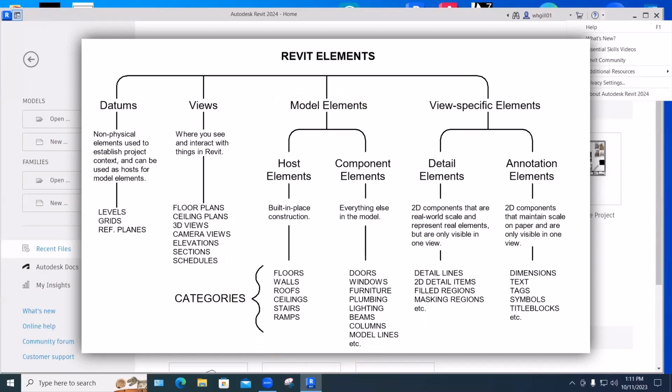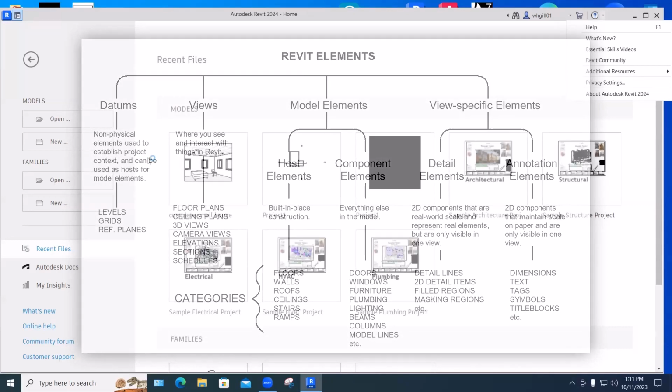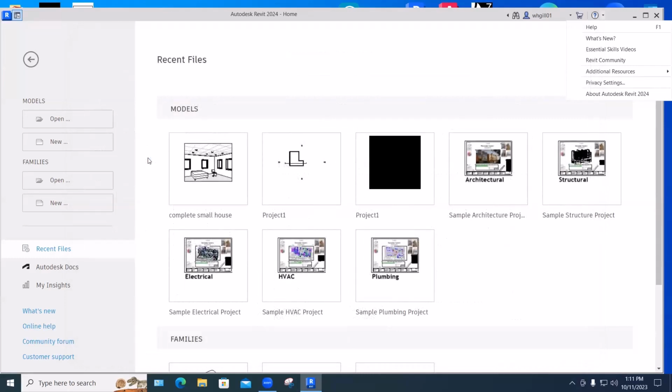We'll look at categories in a little bit, but I'm using the example of a single door, and where that comes from. First of all, there is its category, just of doors. And Revit understands doors as things that take place in walls, not in ceilings, not in floors, that open and shut, and that cut a hole in the wall. Other elements, by and large, don't cut holes in things. You just place a range, it's not cutting a hole in anything. You place a wall cabinet, it's not cutting a hole in the wall, just attached to it. So when we place things, we need to understand first of all where they can go, and second, their place in the organized hierarchy of Revit components.